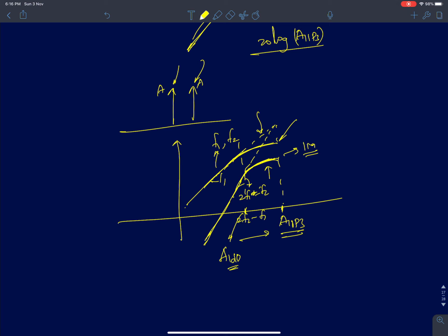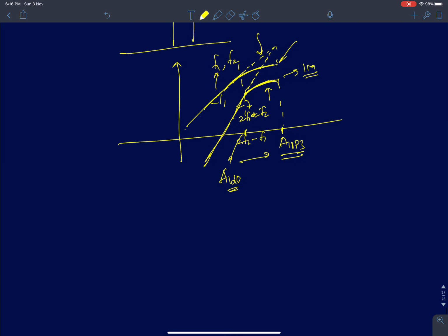So then how do we actually measure IIP3? We just use simple mathematical extrapolation of this graph. Okay, but is there any more efficient way of doing it? Because when you're running this, how far should I run this graph? Those are the next points to worry about. Should I keep sweeping it for different gains? And how accurate is this simulator?